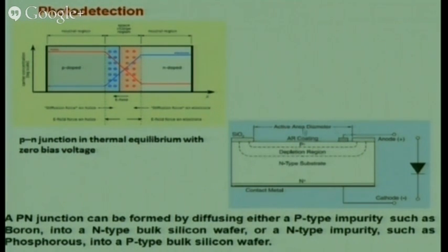The photon which is coming in crosses the p material, gets absorbed in the depletion region, creates an electron hole pair, and now this electron hole pair contributes to the current. So that means a photon is now converted into an electron hole pair, which gives me a photocurrent, right? So if by some means I get this current output, I can measure what the light level available to me is.